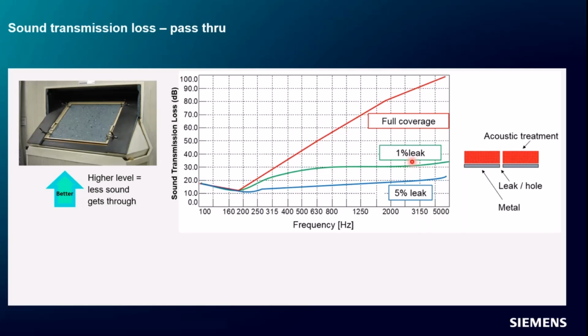So a lot of attention is paid to sealing those leaks and keeping your barrier continuous. If you have gaps underneath your doors in your house, you might have noticed that with almost any gap, it's like that door is not even really there, compared to if you have carpet, where the door makes a better seal. The door actually works as a pretty good sound barrier, depending on its design. But if you introduce a gap at the bottom of that door, the sound just finds that weakness in the barrier and goes right around the door. So something to keep in mind.